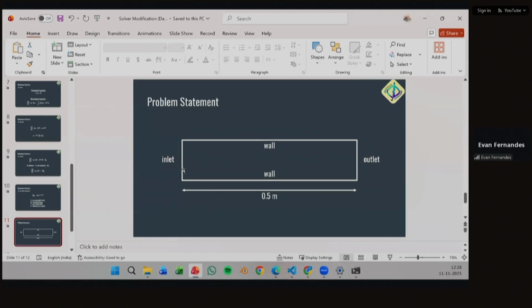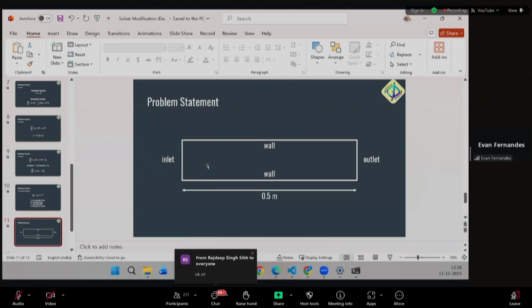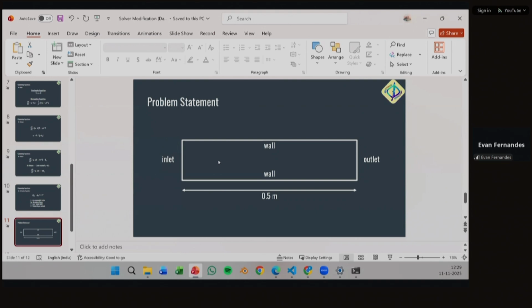But before we do that, we have to first initialize the flow. So we will first solve simple form, just to get the flow parameters out. Then we would solve the energy equation using scalar transport form, so that we get the temperature equations and all of those. And then we will copy those outputs into the input of your scalar transport form, the modified one. Okay, so I will explain that.